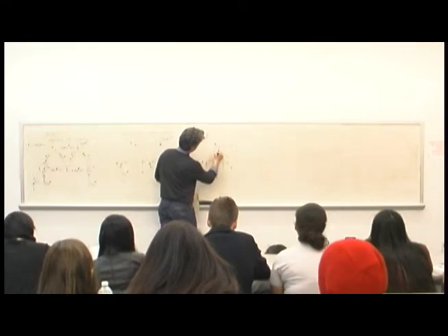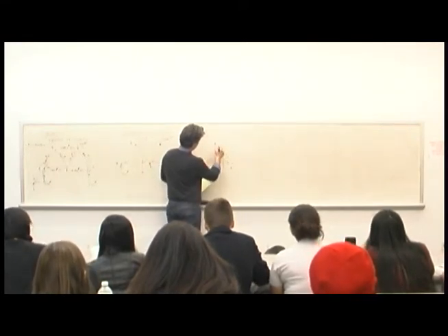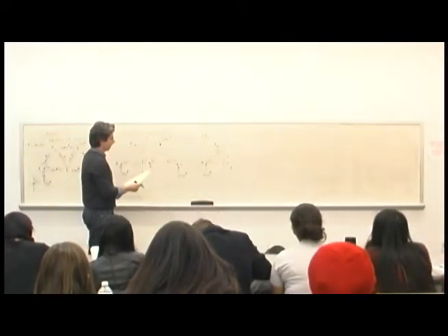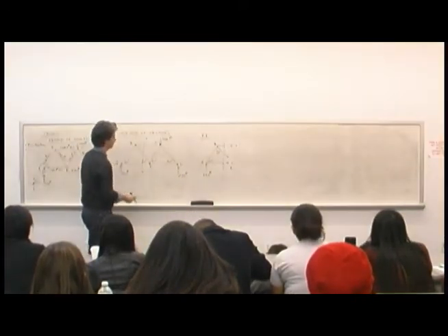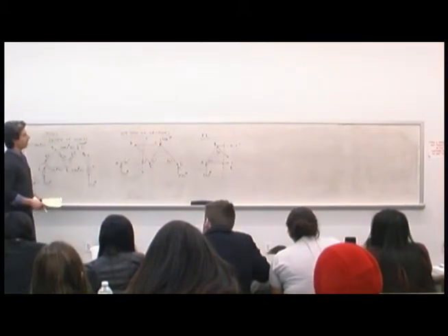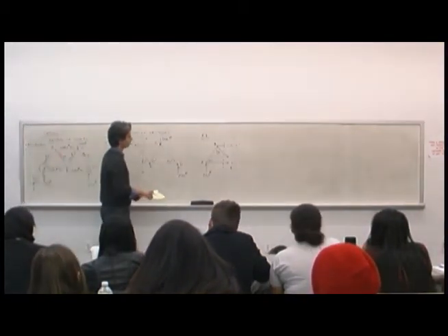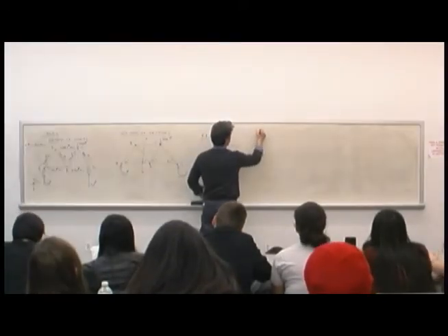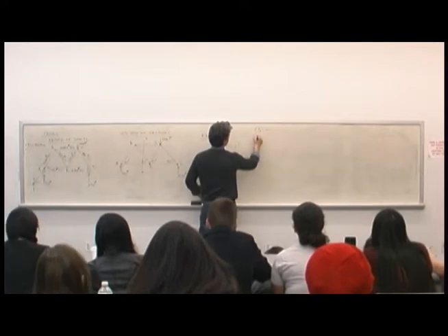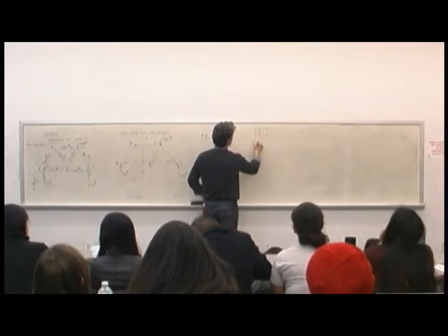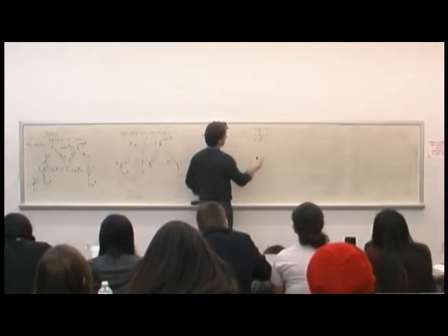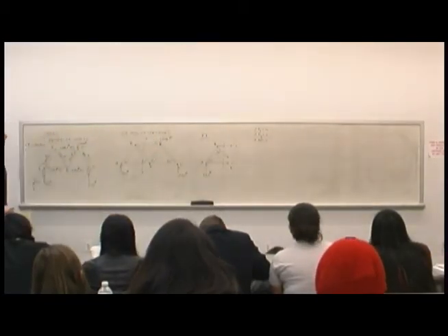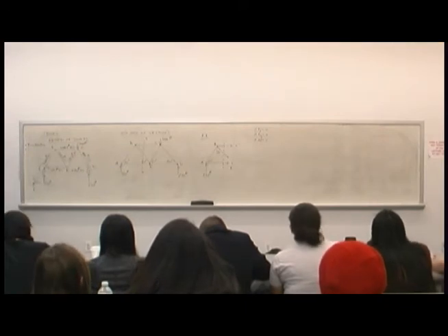So in this problem, what do you say? This is 60 degrees. This becomes 30 degrees, right? So if I want to balance this system, how can I do this? Using equations of statics, the sum of the forces in x has to be equal to 0, the sum of the forces in y equal to 0, the sum of the moments has to be equal to 0. So think of that as just an equilibrium problem.